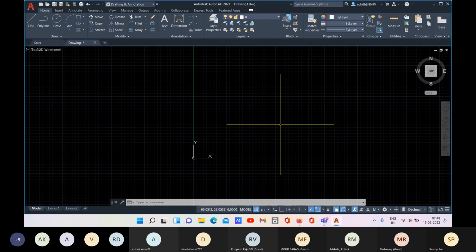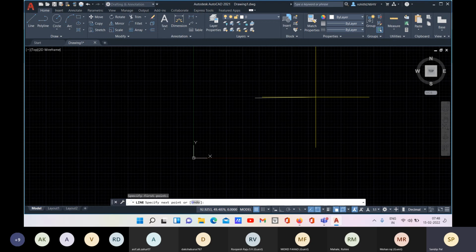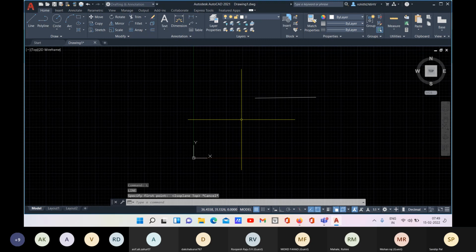If you want to highlight the snap points of any object so that you can place it at the right location, for that we have this object snap, and the shortcut for object snap is F3, and F4 is for 3D object snap. So when you create 3D objects, F4 will be necessary. And we have F5. F5 is for your isometric, so you can activate the isoplanes.